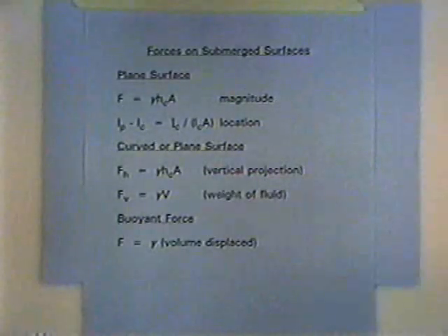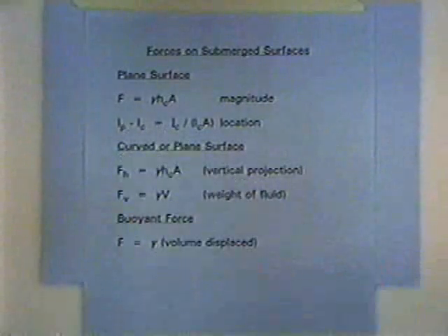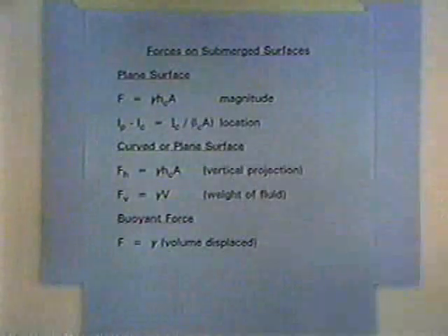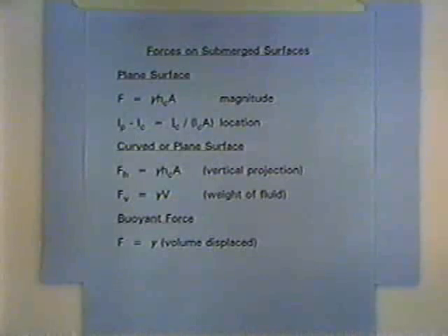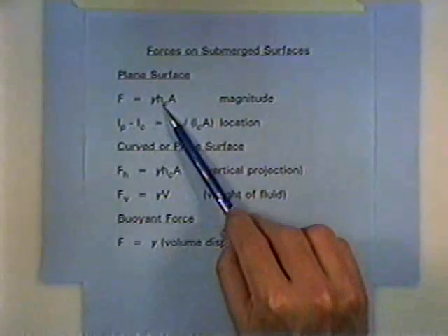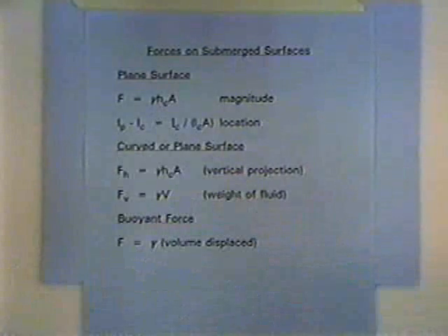And then that example will define the terms here. Notice we'll have a force is equal to the unit weight times the head times the area. Same thing as before. Pressure is gamma times H, unit weight times the vertical height of the fluid column. And then if you want a force, it is the pressure times an area.